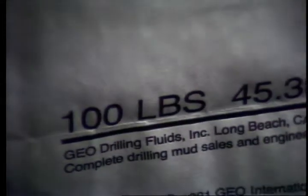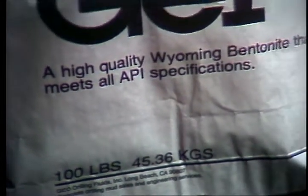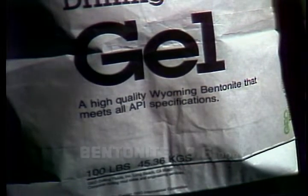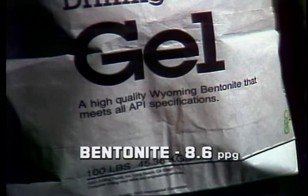But there are varying degrees of flocculation that indicate that there is a problem. It is these changes in viscosity that are why you take measurements of the mud. It is most important that we keep ahead of the mud system. And another thing about the mud that's important: mud weight. Now, bentonite isn't really too good at adding weight to your mud. In fact, it only really gives you a weight of about 8.6 pounds per gallon.